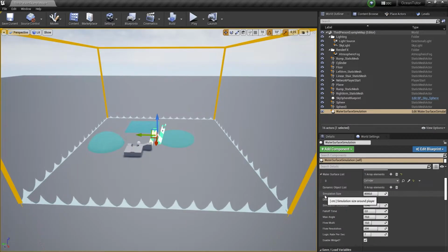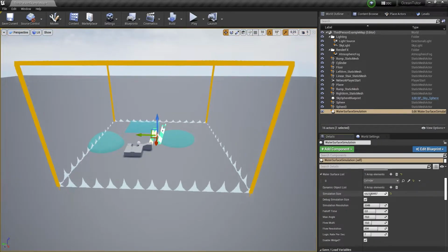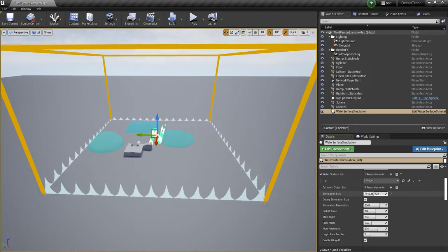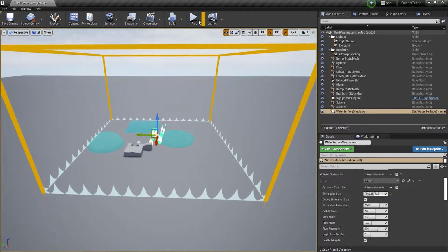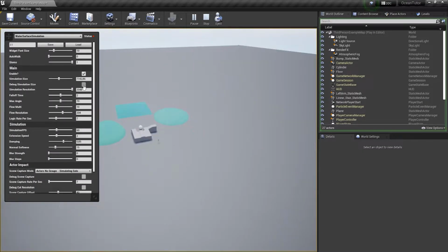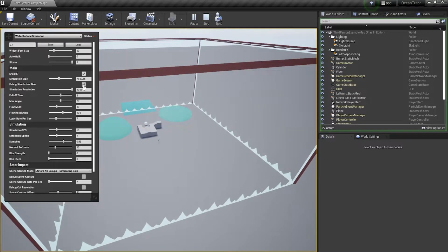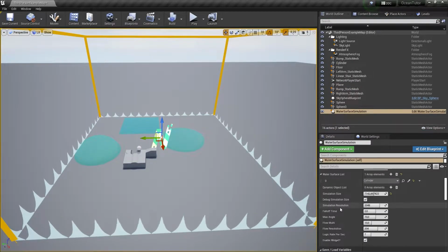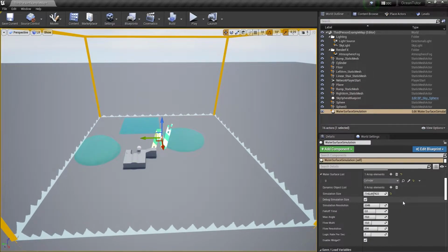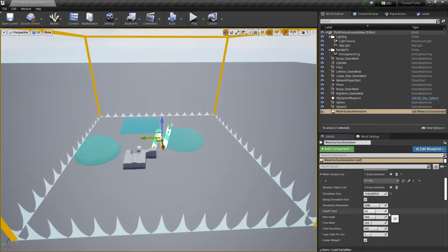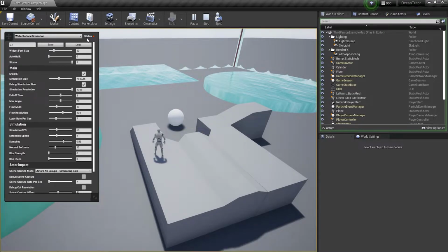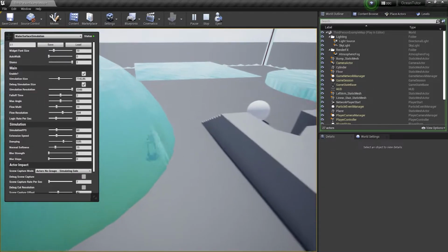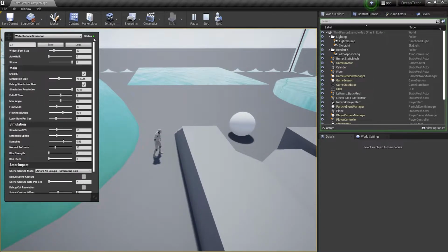The simulation. Simulation size defines the size of the simulation in centimeters. Debug simulation size allows you to literally visualize the simulation size parameter. Simulation resolution defines the resolution of the simulation in pixels. Fall off time is the time that the simulation will wait after it realizes that it can be disabled. You can see the status in the interface by the circle near the status title.